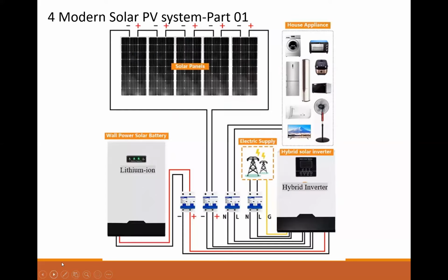But then when we go to lithium, we have got 2 levels. The inverter will control the charging of your lithium-ion battery. And of course, even the lithium-ion battery itself will control the charging aspect. So now this is in line with the power reticulation aspect. Now, when we add a second level of control, where we have got communication between the lithium and the hybrid inverter, then you actually have got optimized operation. So this is one aspect.